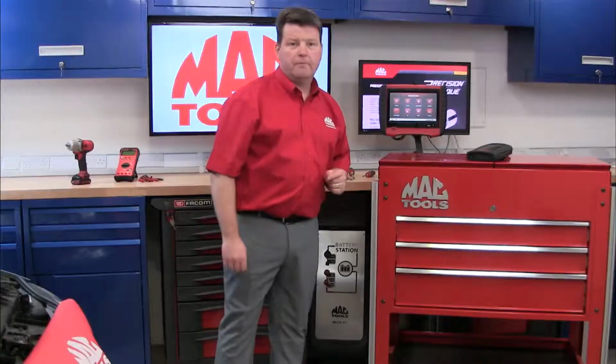These days, the majority of mainstream vehicles have to comply with OBD legislation. This means there will be additional diagnostic data available that's emissions based. It's a separate diagnostic program that meets European legislation and has to be provided by all manufacturers. It may sometimes help with the diagnostic process.